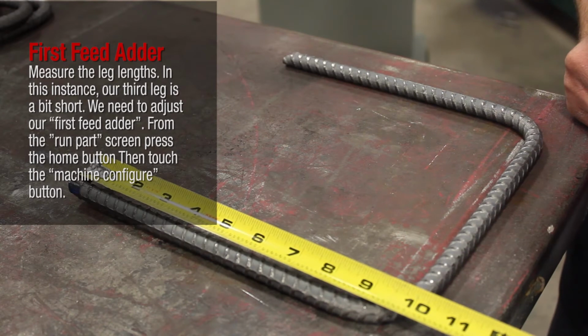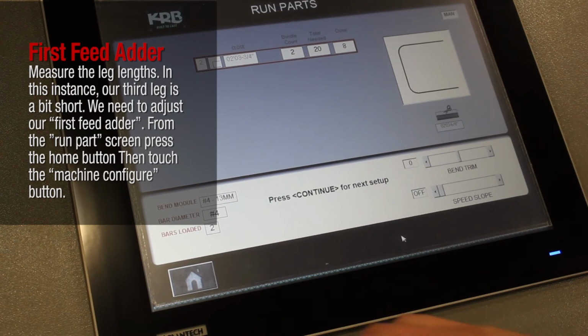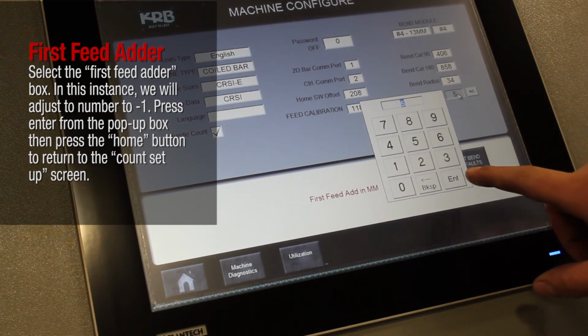Measure the leg lengths. In this instance, our third leg is a bit short. We need to adjust our First Feed Adder. From the Run Parts screen, press the Home button. Then touch the Machine Configure button. Select the First Feed Adder box.